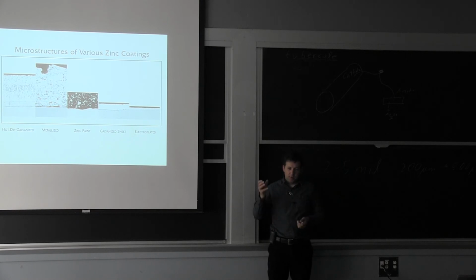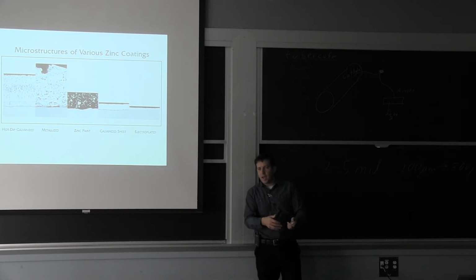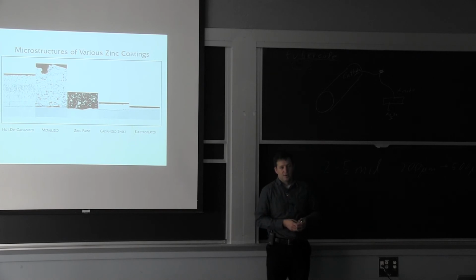even if you have a little bit of penetration of moisture into the system, it doesn't create that big reaction of corrosion of the steel because the zinc is there. So you win both ways. In areas where it's protected with the paint, the paint doesn't come off because you don't have a reaction at that interface.